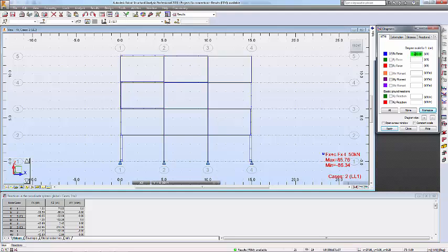If you want a better view, let's increase this by 4 times, to maybe 800. So click on apply. Oh no, sorry, that's the other direction. So let's change this one to 100, so maybe 2 times bigger. This looks like quite a clear view of how the structure transfers the force from one end to another by the rigid connected beams, and they form a rigid frame structure to withstand the lateral loading you apply. Okay, and the moments are shown here.